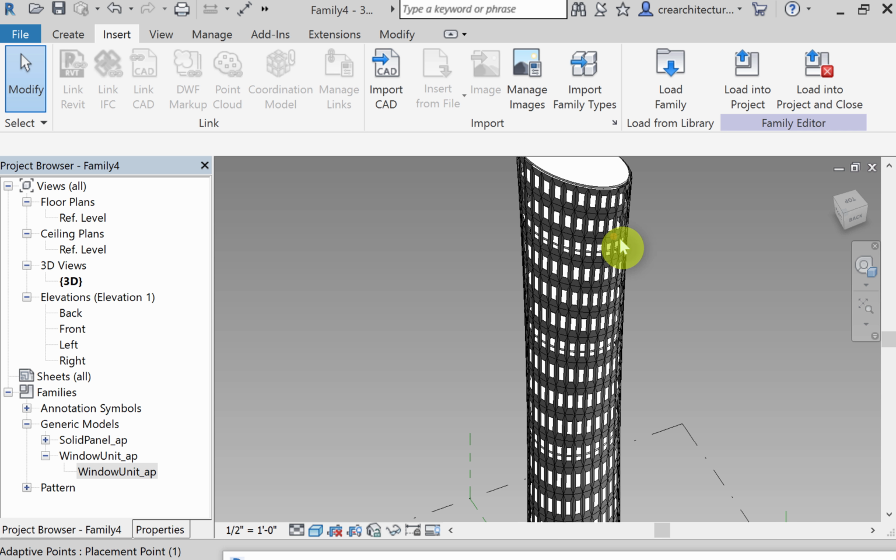You know the other thing you could do? You can put a glass. The glass is going to be a four-point adaptive component with a glass material, and give it a thickness. It has to be with the thickness. You cannot change the wall thickness after, so we'll have to do it at the adaptive component. Okay, so now we have extra space over here because the wall is not thick enough. And it's okay. When we do the renders, I don't expect you to have any